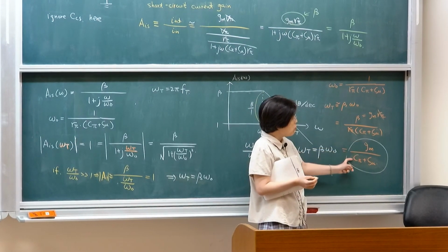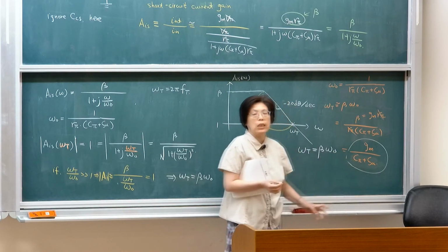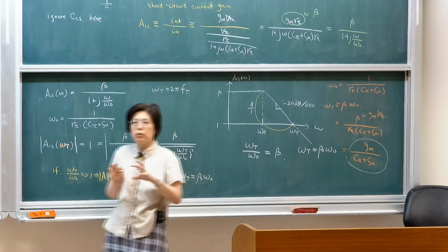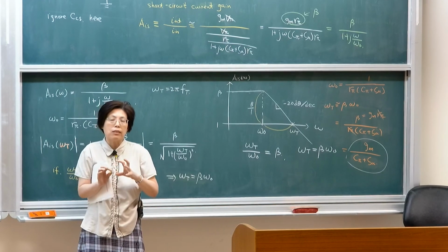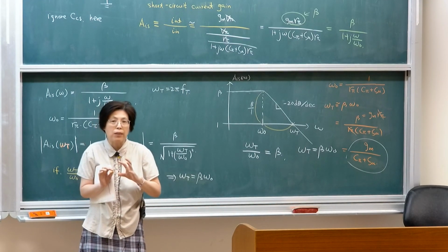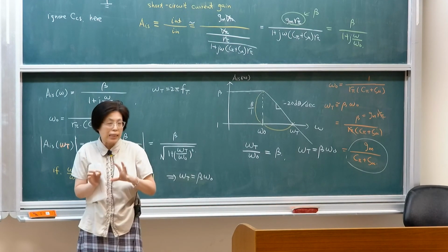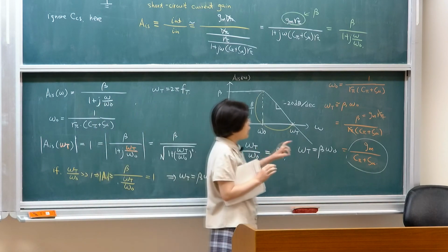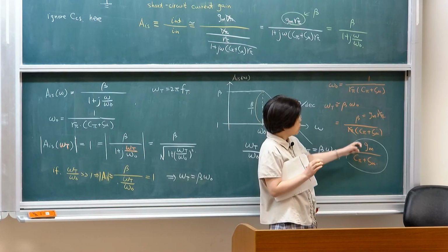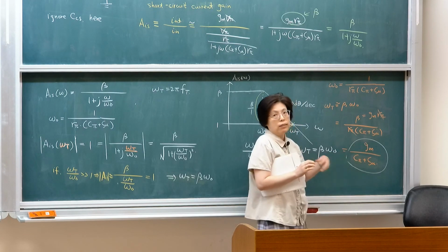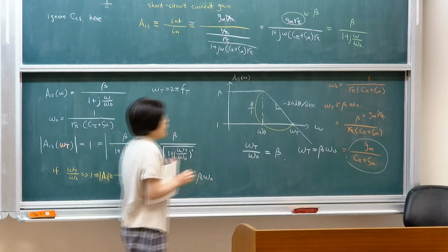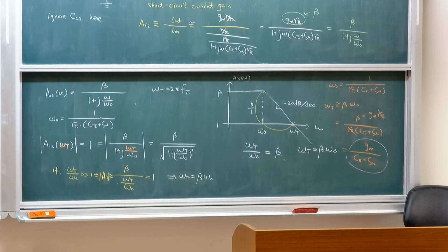At a particular frequency, the conductance of the parasitic capacitance exceeds that of the active device. You would then no longer see the effect of the transistor. So the transistor is being shielded by this parasitic effect. It's a competition between the two.